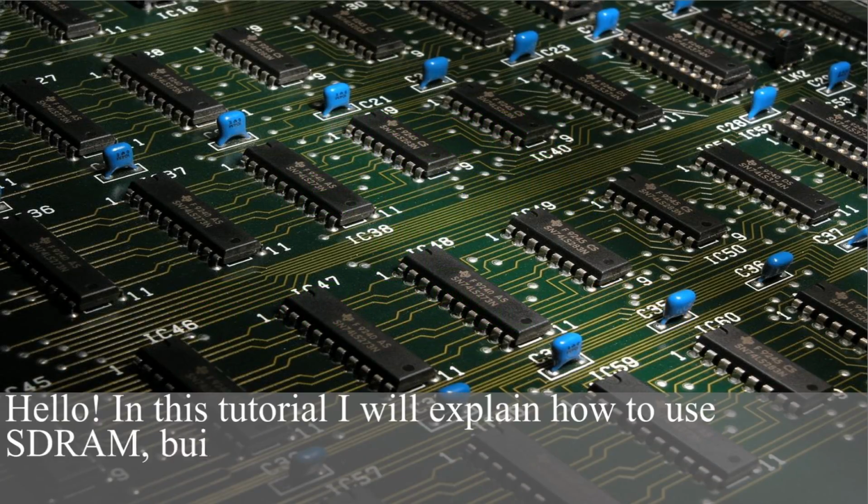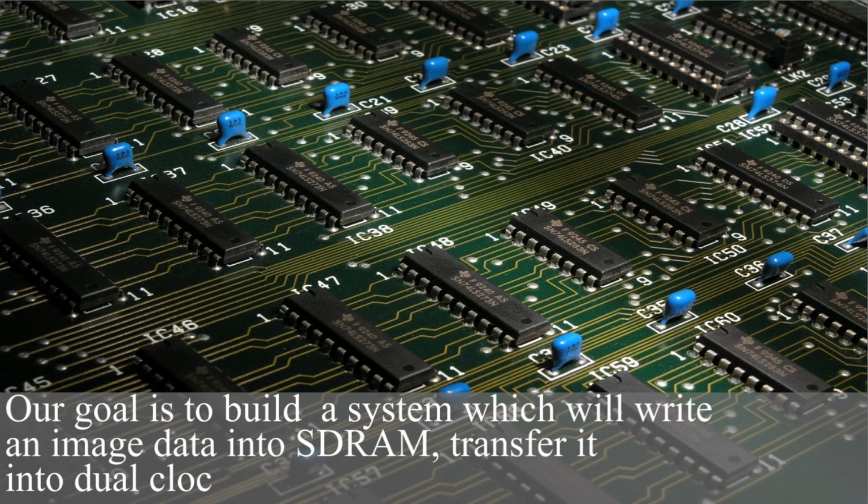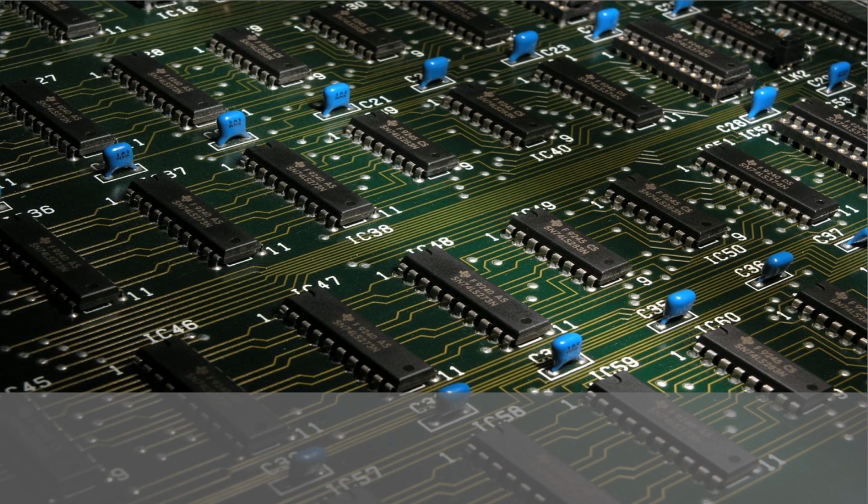Hello, in this tutorial I will explain how to use SDRAM, build a dual clock FIFO and deal with signals in multiple clock domains. Our goal is to build a system which will write image data into SDRAM, translate it into a dual clock FIFO and eventually display it on an FPGA monitor.